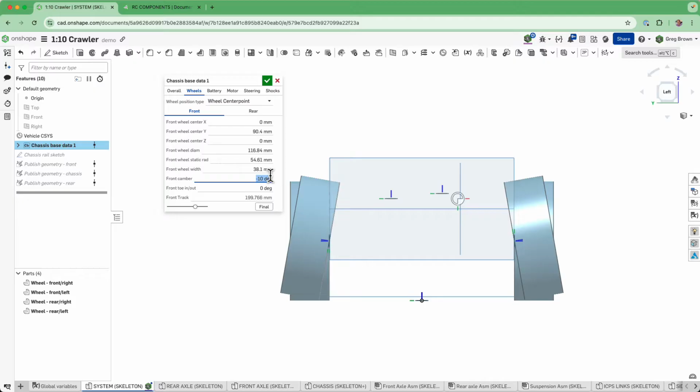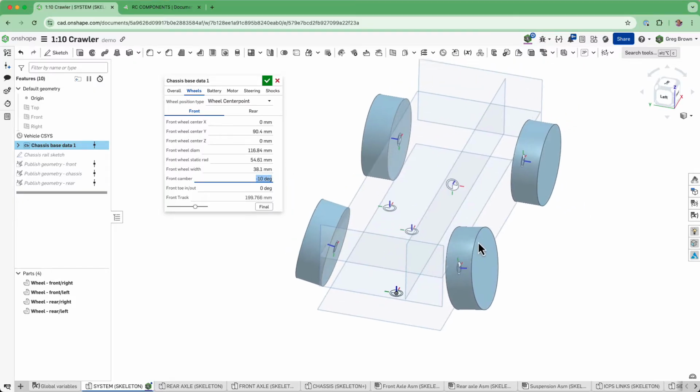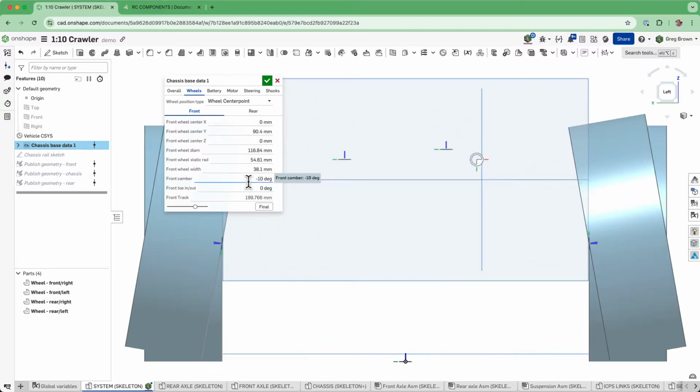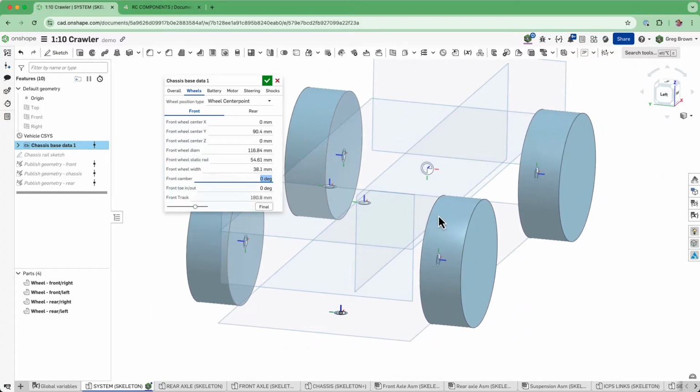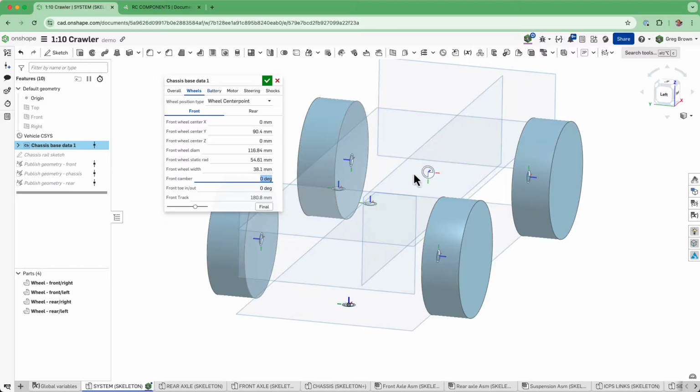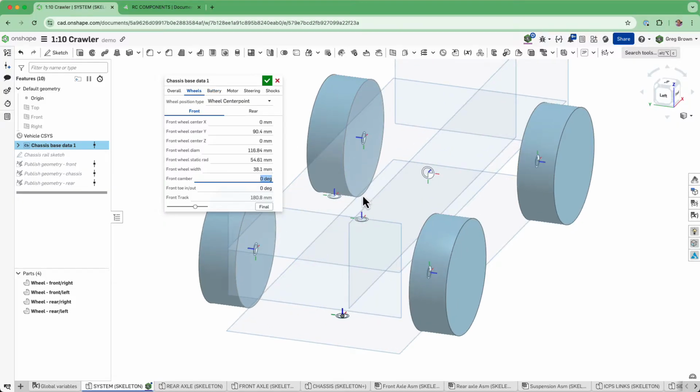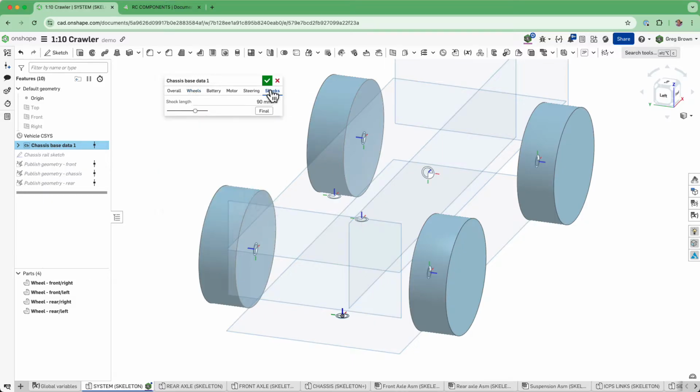And at my skeleton level, you'll see how these really gross, large-scale space claims, if you will, are being updated there. So let's just go to straight up and down for the moment. I've got similar pages here to ascertain the position of where the motor is going to be or the steering axis is going to be, and a very simple one about the length of the shock.